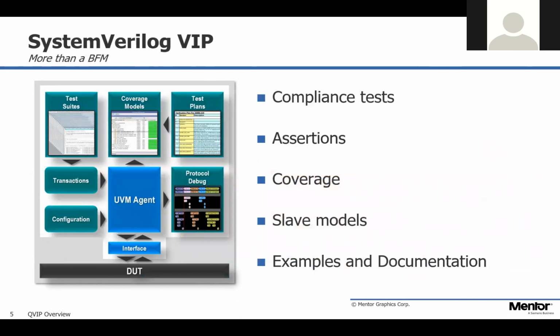It means that we can now start to create verification IP. Everybody is using the same standard, and that way we can create this piece of verification IP that can be reusable across projects, and from block level to subsystem level to chip level, etc.